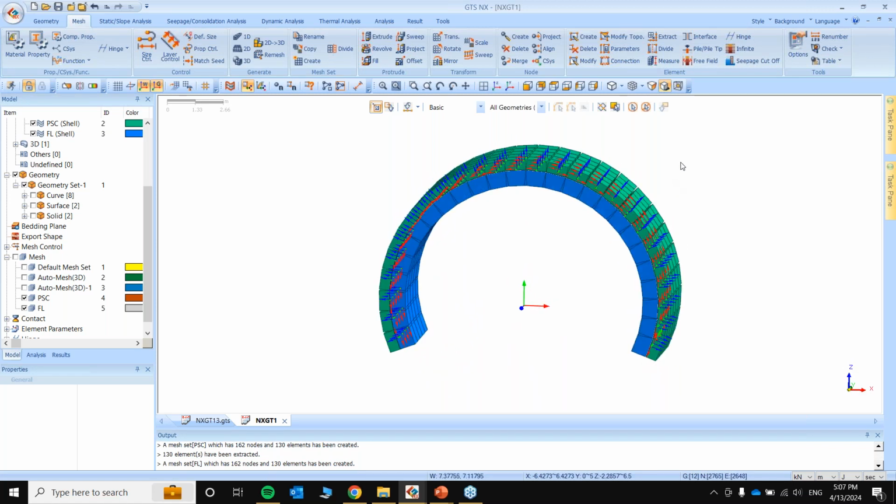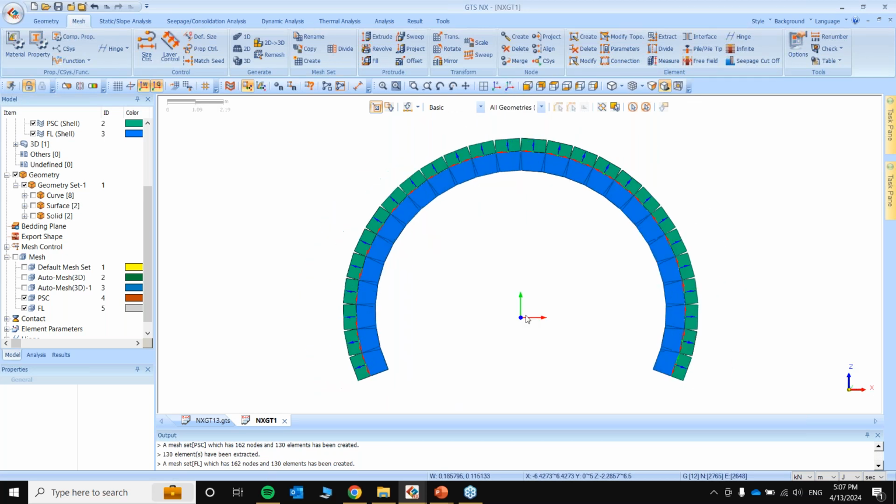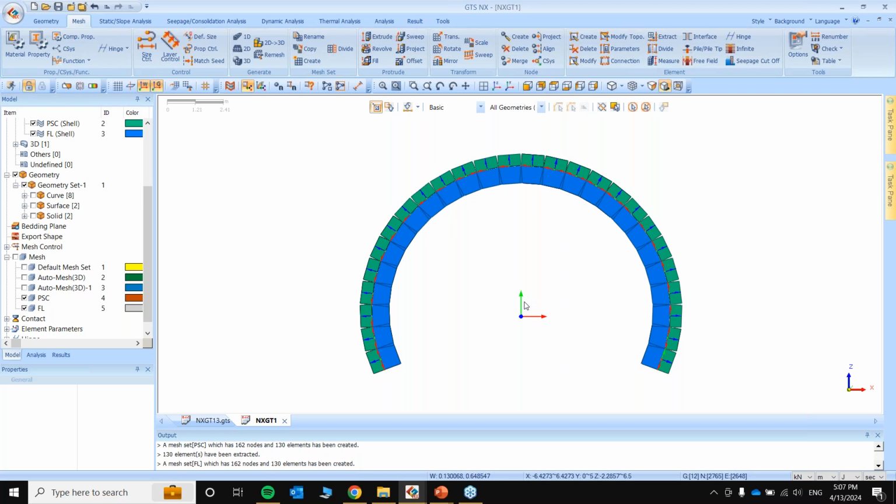I hope this part is clear for all of you, because to allow interaction between both the elements, this is the easiest and fastest way to do it. Here, since you are modeling them as plate elements, you'll get all your element results like axial loads or the hoop stress, and also the shear forces and bending moments. Otherwise, if you go for the solids way, you can also do that. Not a problem at all.